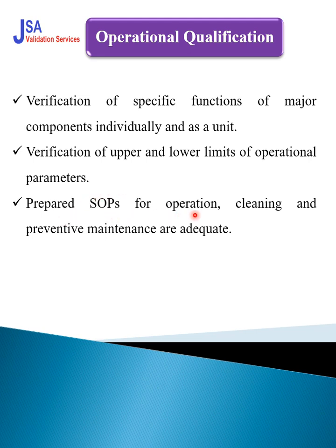Prepare the SOPs to confirm that operation, cleaning and preventive maintenance are adequate. The SOPs we have drafted, we challenge the operation of the equipment through the draft SOPs for cleaning, preventive maintenance and breakdown handling, so that we know the SOP is able to perform the task and is easily understandable. If there is any amendment in the SOP, we can do it in the draft stage, and the final draft will be prepared before going for the PQ. The SOP should be effective.